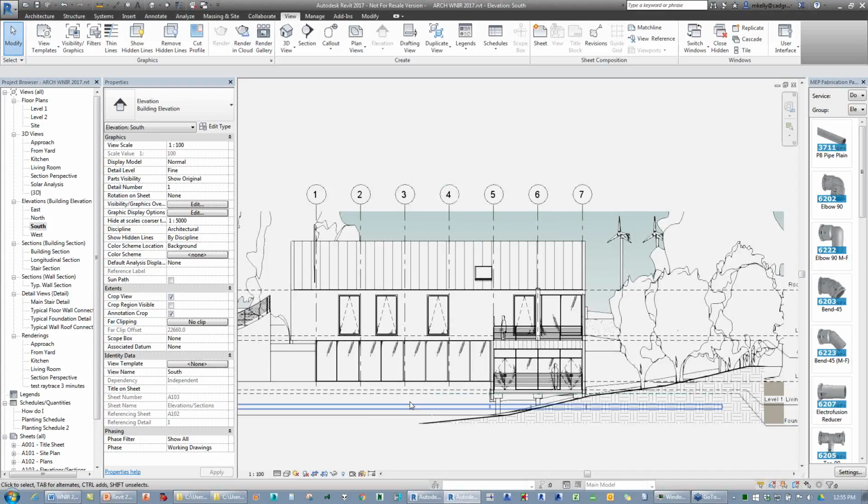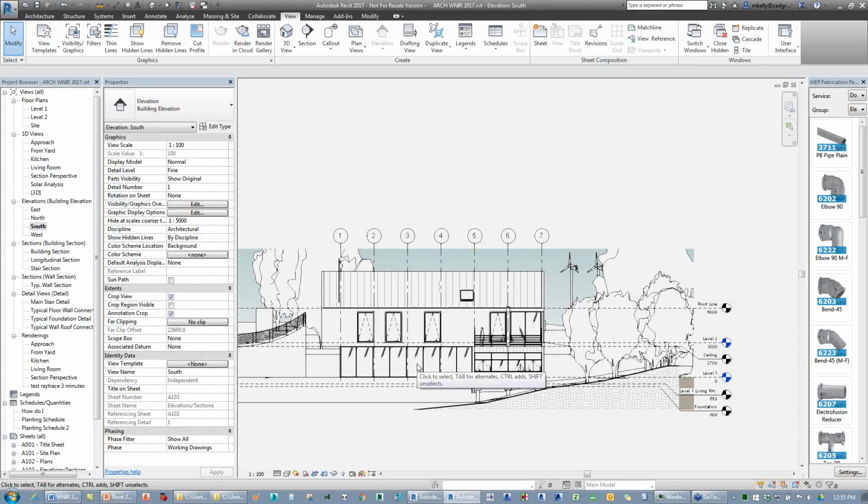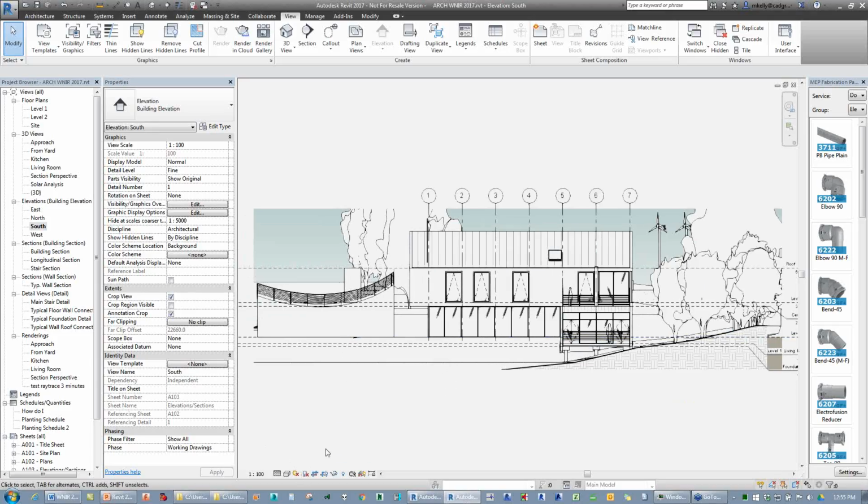It's really just going to become pretty much just the black and white portion. So yeah, that's an interesting thought. And Revit XT would be exportable using vector for sure, because it's affecting the line weight. But the two together, I think you are going to have to use raster, because you won't be able to get that shading information otherwise.